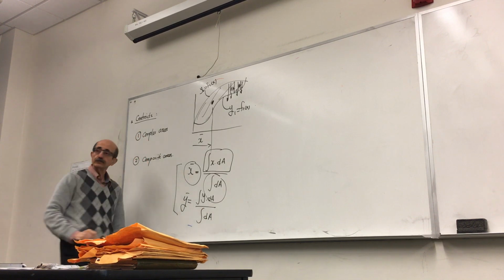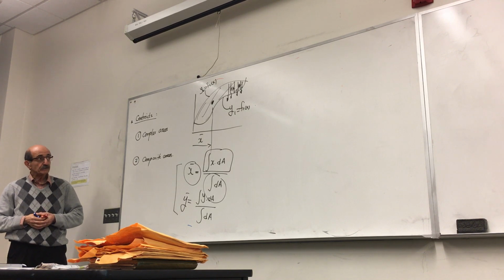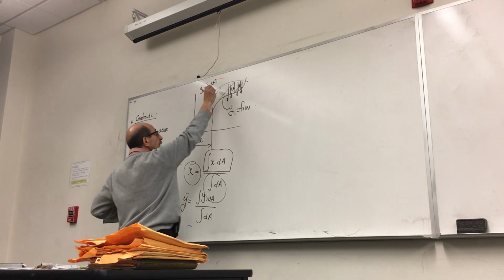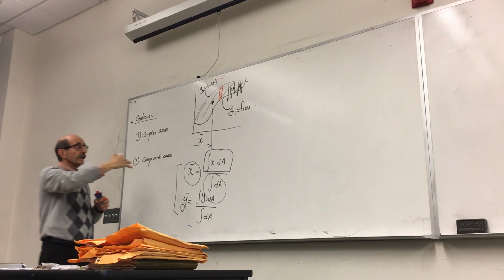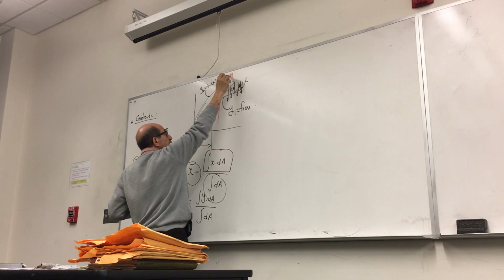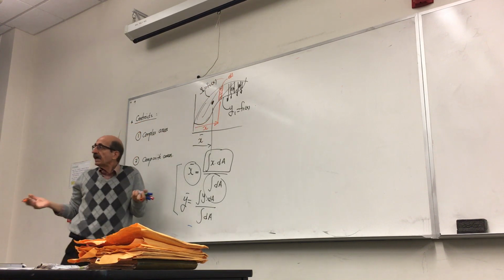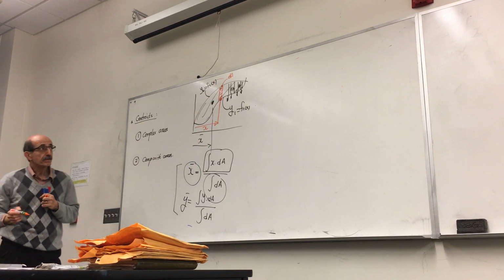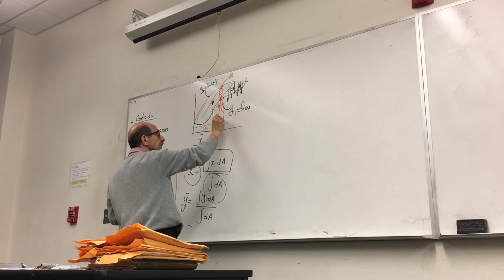So how do we calculate these? In order to demonstrate that, I would start with an example. But let me in general first say that for x bar, you always consider a differential area whose sides are parallel to the y-axis. In other words, you identify a general differential area which is located at the general position x, meaning that at any point here or any point here, right? And the width of this is obviously a dx.